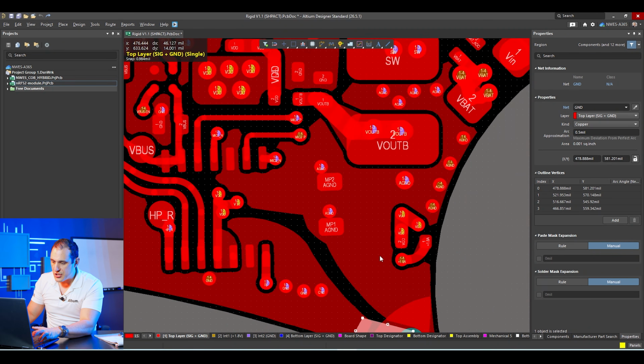So what I would recommend, first thing you do is, if you are going to have a connection between two different ground nets like this, create a net tie component. That way you don't create a short circuit error inside of any CAM tool that then analyzes the netlist output when you create your manufacturing files. Now, why do we want to avoid doing this?